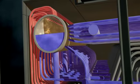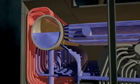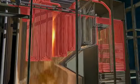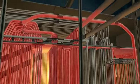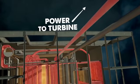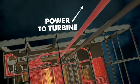Because this saturated steam still contains small amounts of liquid water that would cause corrosive damage to the turbine, the saturated steam is routed back into the firebox and through superheaters to burn off all but the smallest traces of liquid water. This dry, superheated steam then exits the boiler, passing through a steam header and ultimately providing power to the spinning turbine, which generates electricity.